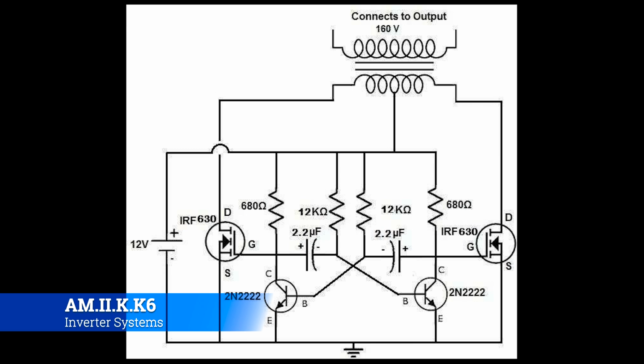All right, so we're not going to get too far into the details about how an inverter works, but effectively this is it. We're going to use different transistors to open and close different gates to help produce a nice smooth wave. Well, a ripple effect, and then the capacitors get employed to actually smooth it all out. So we have this nice solid power band that comes off of it. Just know that an inverter uses comparators, capacitors, and transistors all to make it work.